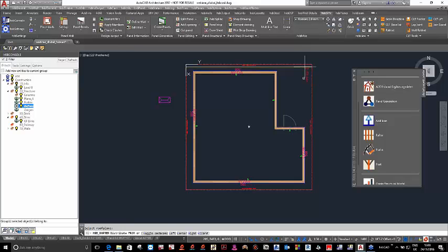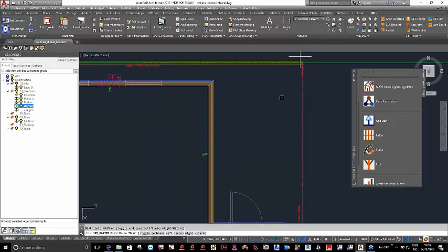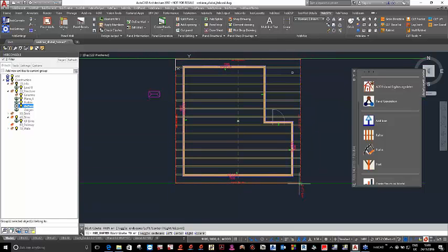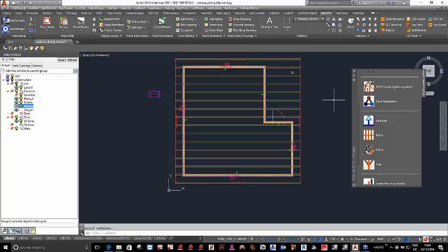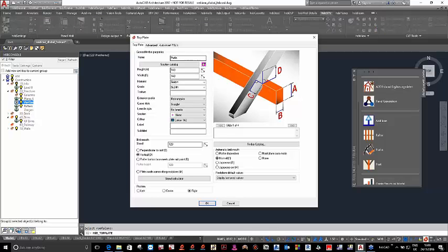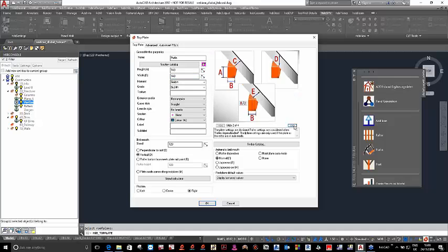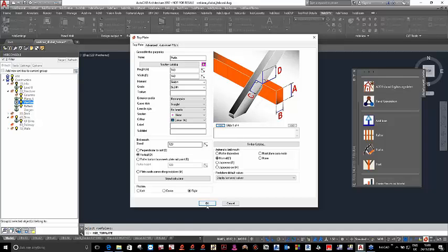I accept that. I'm going to select my starting point and the end point. After that, I'm going to create the purlins that will support those rafters. We'll select my plane again. Once again, all these values have been already preset up, but basically you need to fill all this information. The pictures are quite self-explaining. We'll say OK.